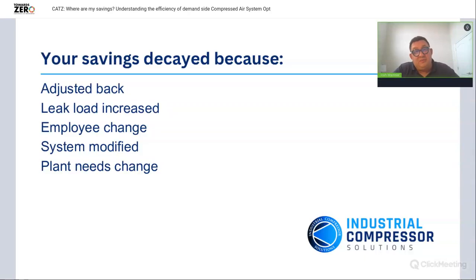System modification is funky to me. It happens all the time, and God knows I've done all of these things personally. I hate to say it, but with system modification, how many times have we serviced a piece of equipment, or realigned a compressed air system one way or another, and then didn't return the valve lineup completely to the way it was beforehand? If you leave a bypass open, something simple,